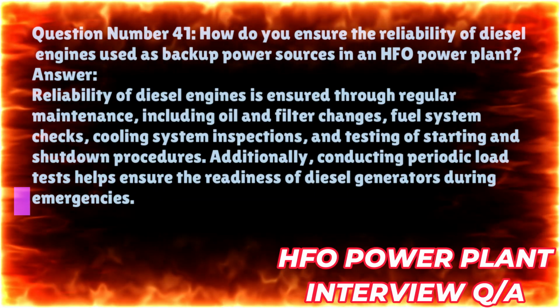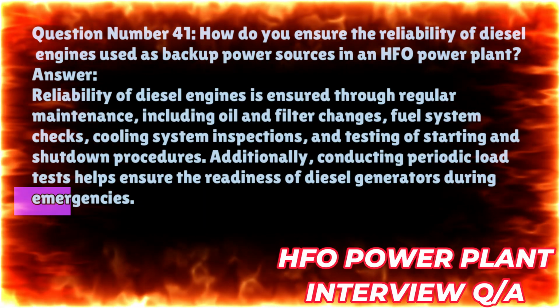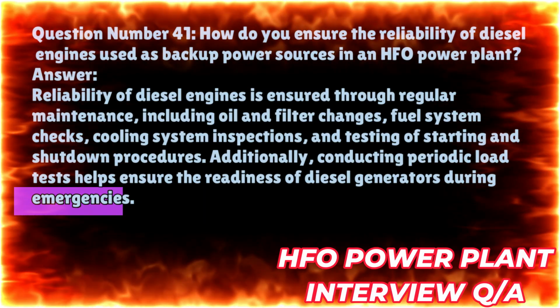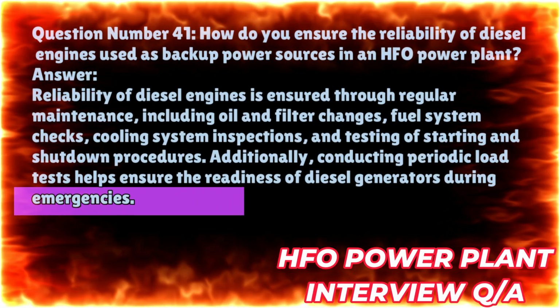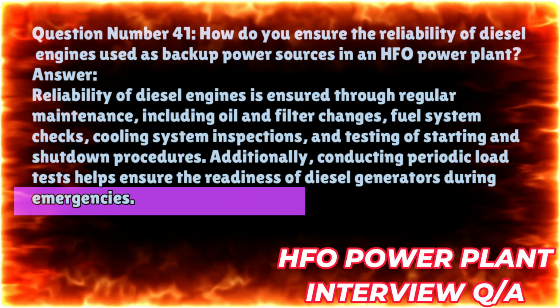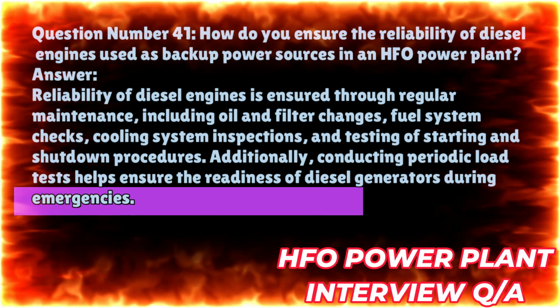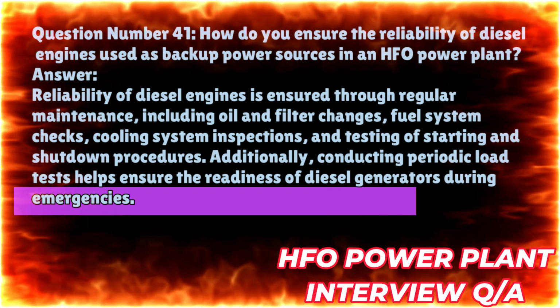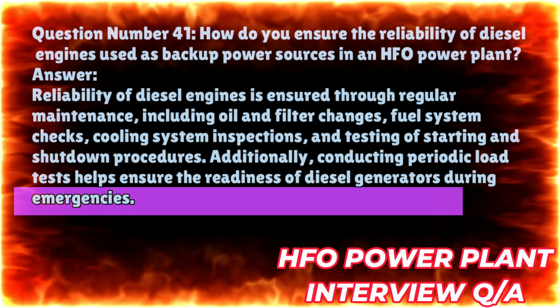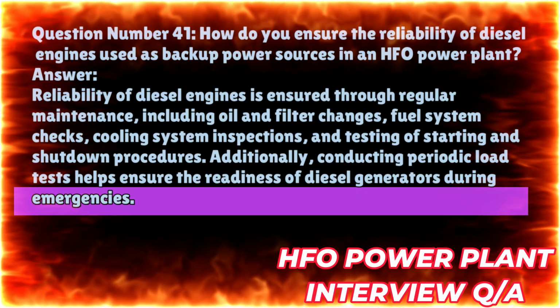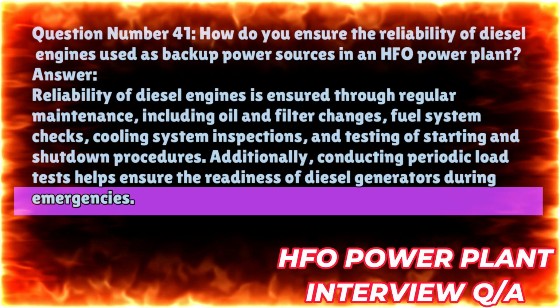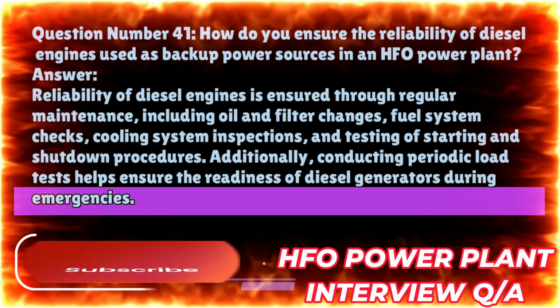Question number 41. How do you ensure the reliability of diesel engines used as backup power sources in an HFO power plant? Answer. Reliability of diesel engines is ensured through regular maintenance, including oil and filter changes, fuel system checks, cooling system inspections, and testing of starting and shutdown procedures. Additionally, conducting periodic load tests helps ensure the readiness of diesel generators during emergencies.